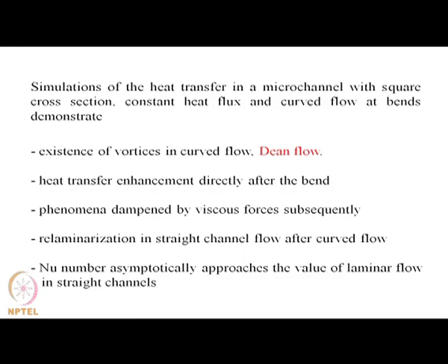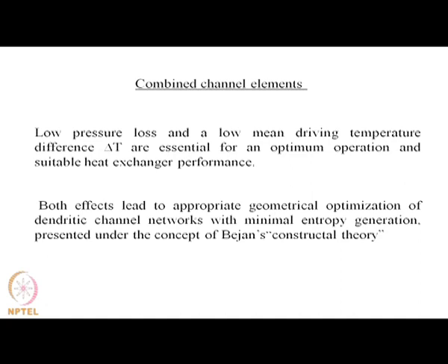And finally, the Nusselt number will asymptotically approach the value of the laminar flow in straight channels once you flow past such bends. So, if you have combined channel elements, then what you would want is low pressure loss and low mean driving temperature difference, so that you can enhance the performance of a heat exchanger.